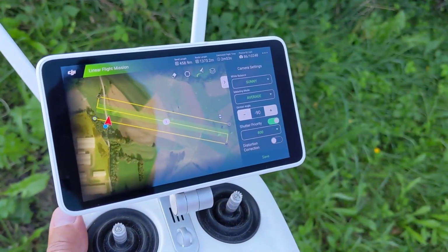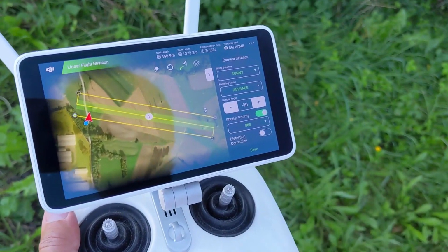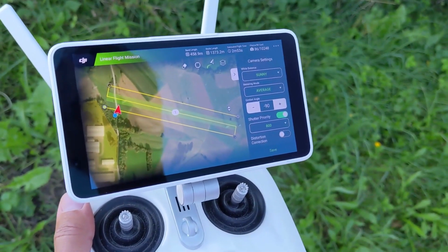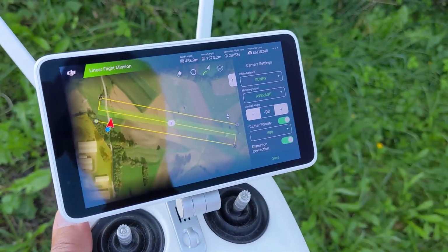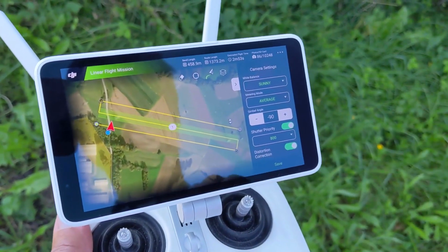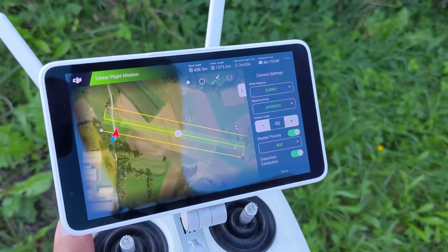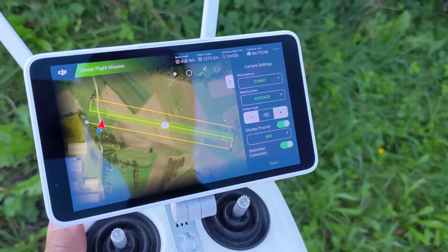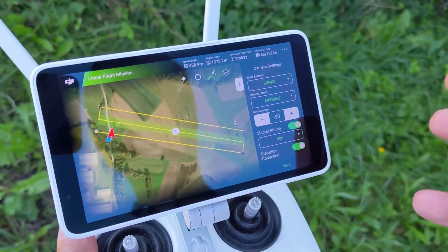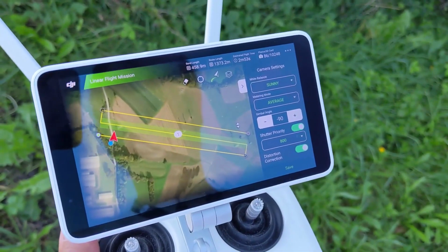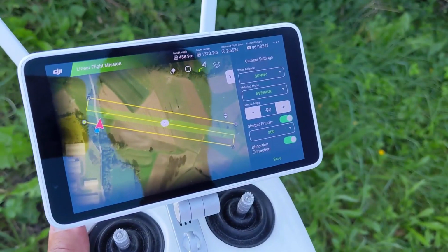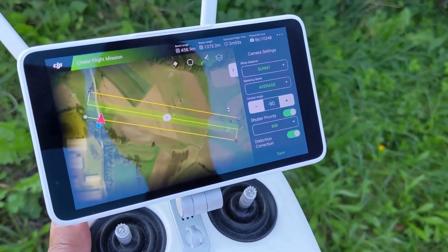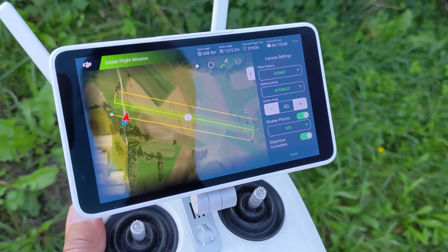So check out this one. And always when you map with a DJI RTK drone, use distortion correction on. This will give you more accurate data, a nicer orthophoto, and faster calculation. In this case the drone is already calculating the first camera distortion based on parameters, and then later in the 3D survey software we do it again, but it's just more effective, everything.